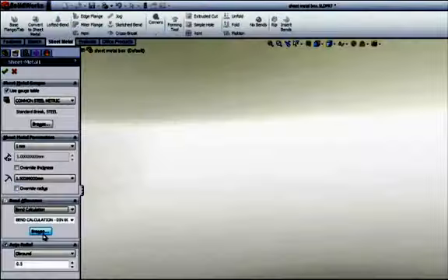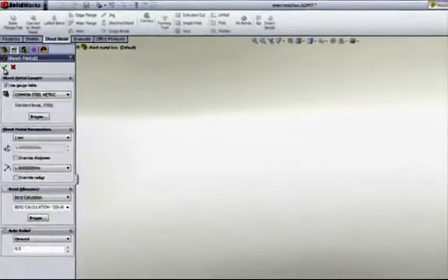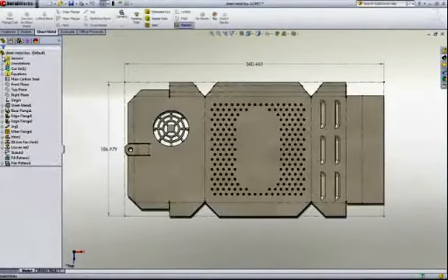Flat patterns can be calculated by using a bend table, K-factor, bend allowance, bend deduction, or bend calculation. Bend calculation tables are very important, as you can define different angular ranges, assign equations to those ranges, and calculate the developed length of the part. Changing the way bends are calculated changes the blank size.